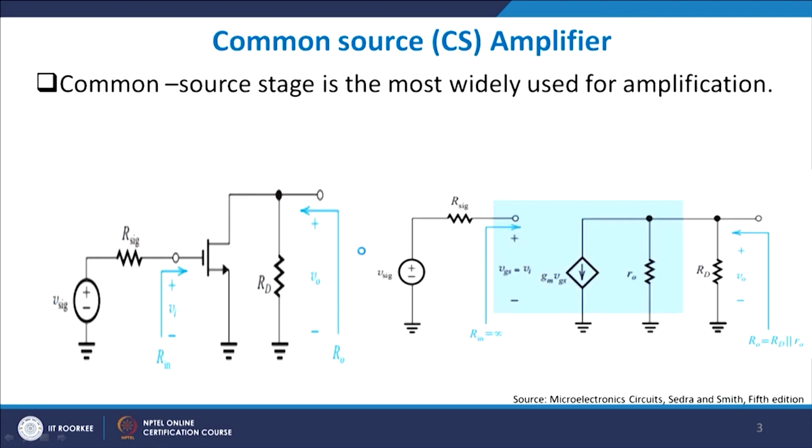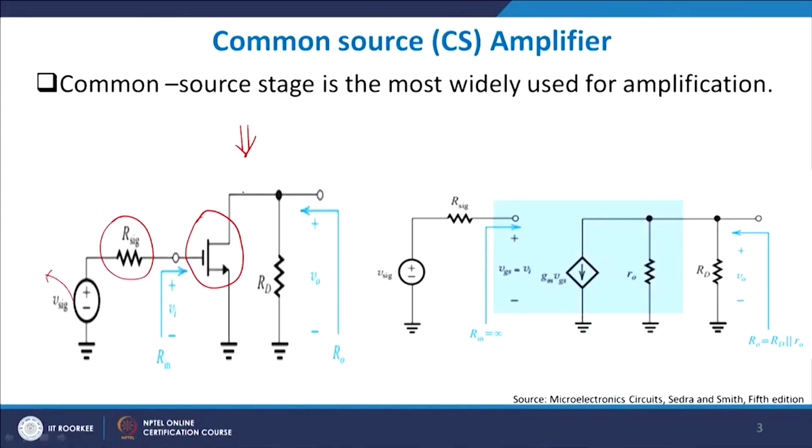This is the diagram of a common source amplifier. You see here you have an NMOS device, which is this one. This is the active device, and this is the output resistance of the input signal source. So, this is the signal source which is there with me. Assuming that I have already DC biased it, which means that I have already fed these devices with an external VDD supply and source supply and biased it in the saturation region, so that it works as an amplifier.